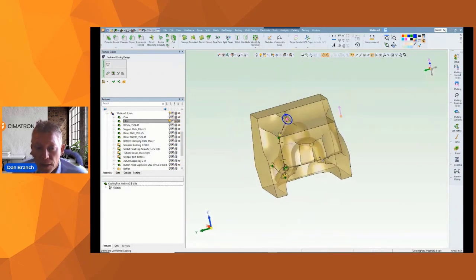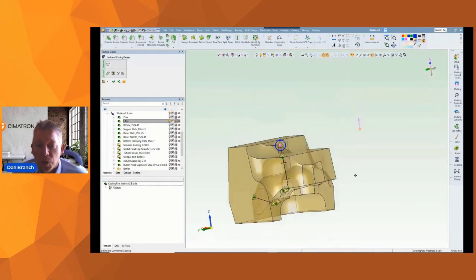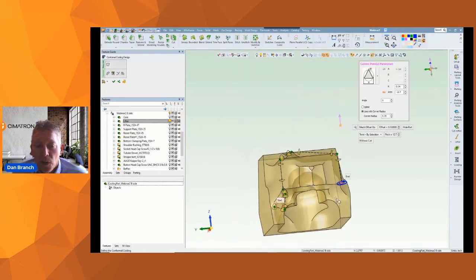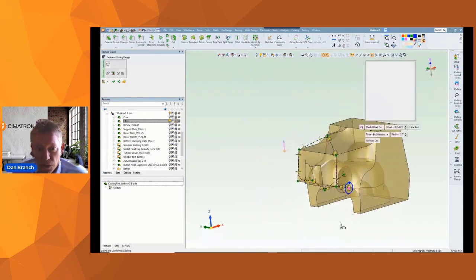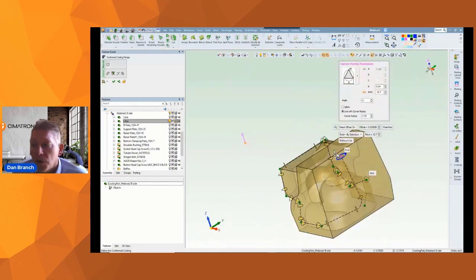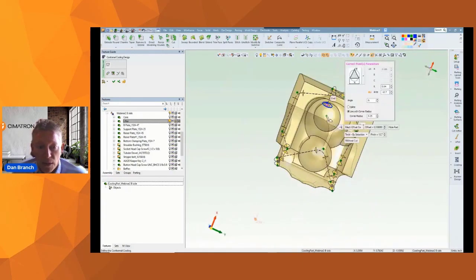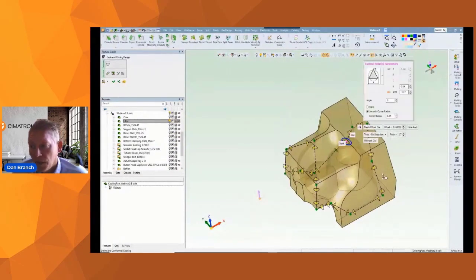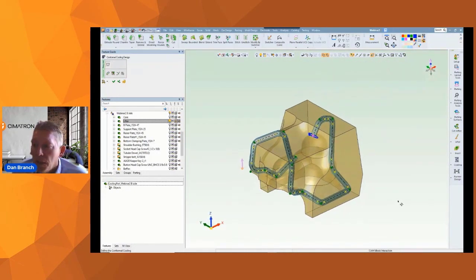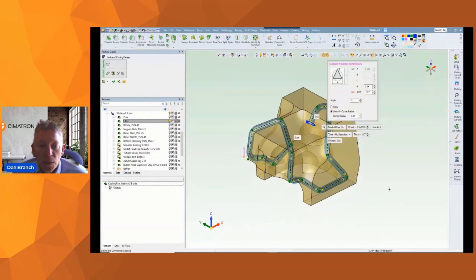At every point along the path, the section is previewed, and I have that dialog available. So that provides for a huge amount of adjustability in the channel size and the channel shape. You can even turn on a parameter to continuously twist the channel. So that provides even more variety in turbulent water flow. I'll preview it. And that would be the proposed conformal cooling channel.